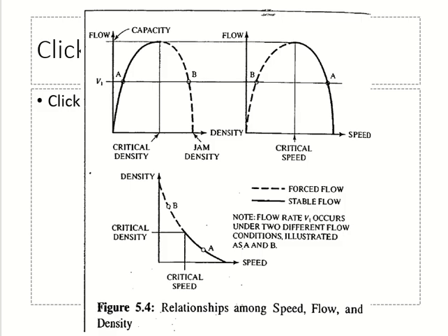Flow is zero because there are no vehicles on the road. If there are virtually no vehicles on the road, then the speed will be very high, right? You come on the road and you can drive at the design speed or the speed limit. So the speed is very high, but the flow is very low.